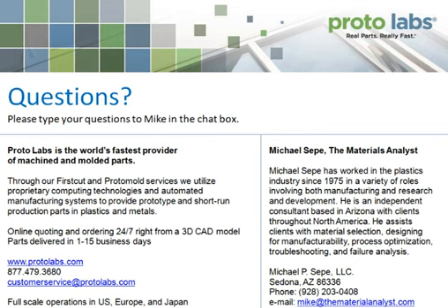People I know today who are using liquid are having very good success with incorporation. And I think that's just representative of the fact that liquid coloring has come a long way. But viscosity matching is still an important issue. And so, different liquid color suppliers perhaps bring a different skill set to the problem.